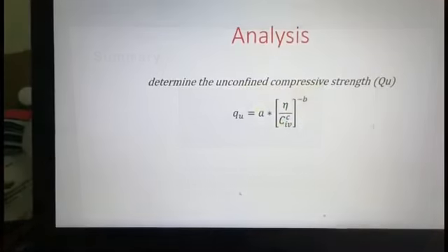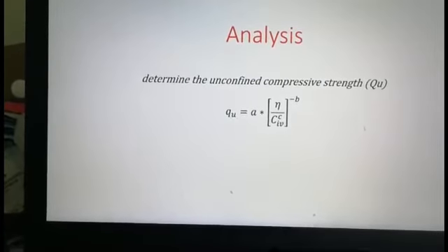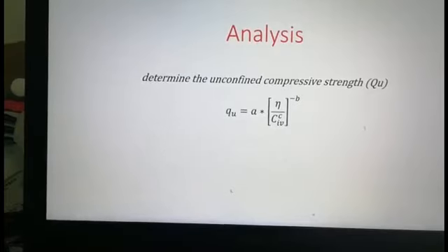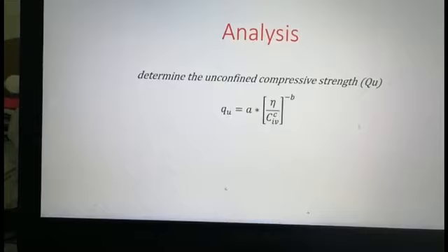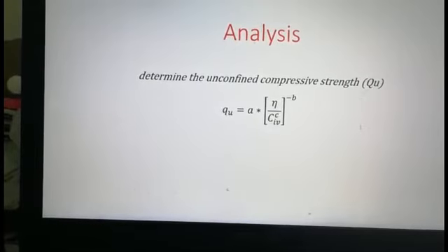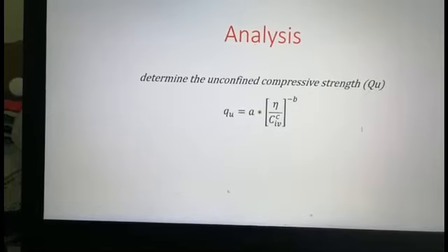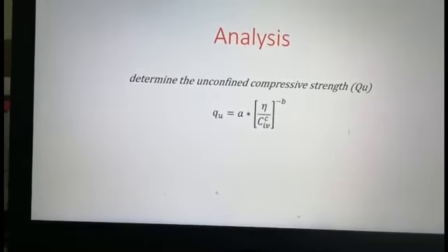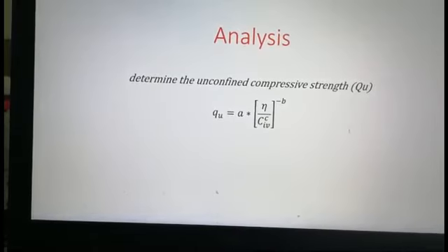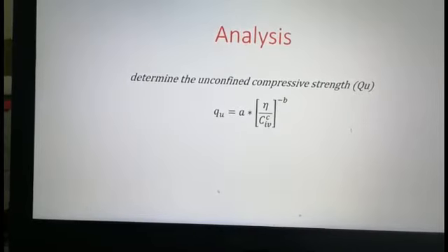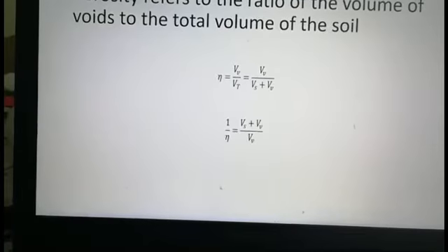Thank you. Now let me talk about the analysis of our report. In order to determine the unconfined compressive strength QU, this research will be using the numerical method by the function of the relationship between QU, porosity, and volumetric cement content. The equation is shown on the screen.